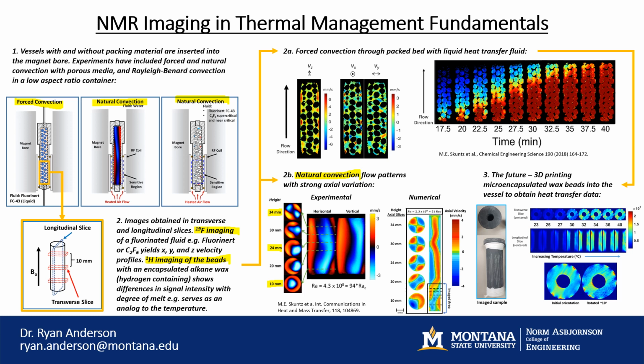So depending on the Rayleigh number you have there, that's a function of your temperature that you apply between the top and the bottom and the particular fluid you're using, we get these different pattern variations. We also see something really similar numerically. All of this work has a numerical complement, so this is just one result that's shown here.